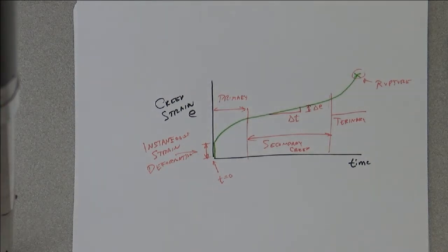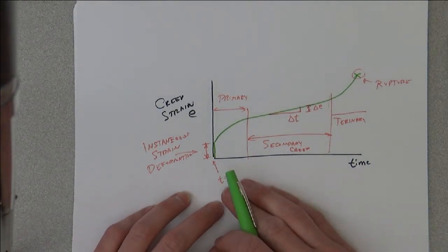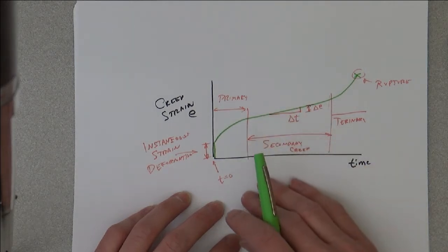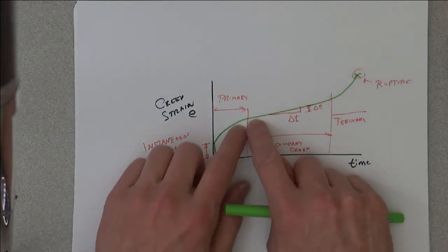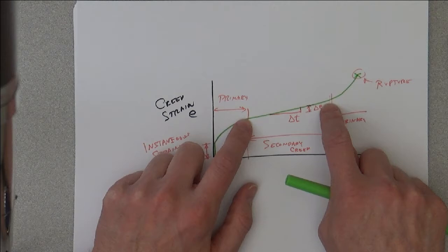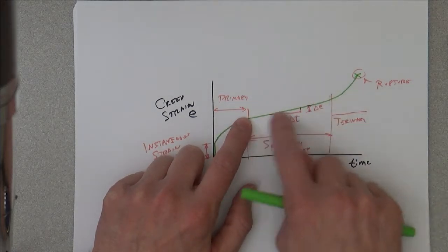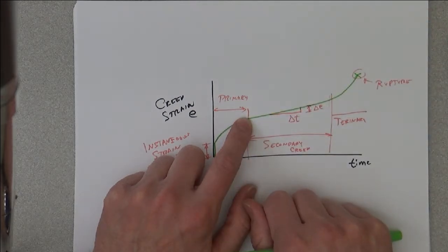One of the primary mechanisms of creep is through the diffusion of vacancies in a crystal, and you may have these just getting started. You might have, say, a surface that acts as a source of vacancies, and they start turning on. In this middle region, we have most of the lifetime of the part in which we have this kind of slow diffusion of vacancies.